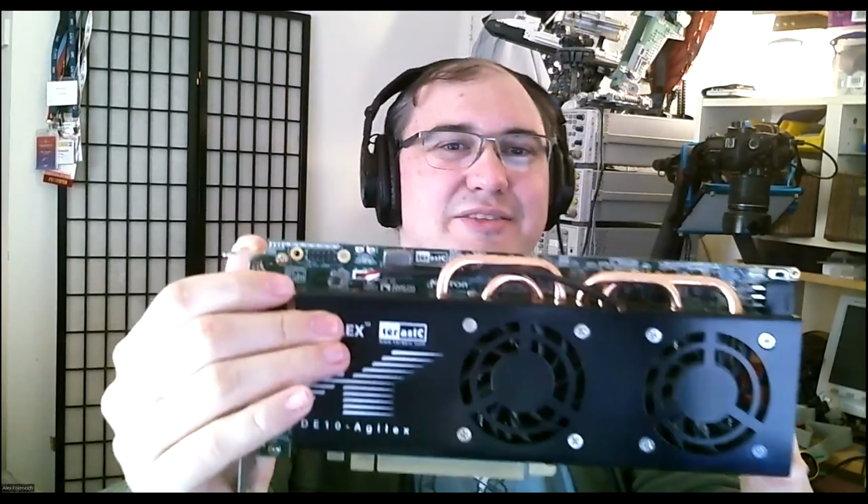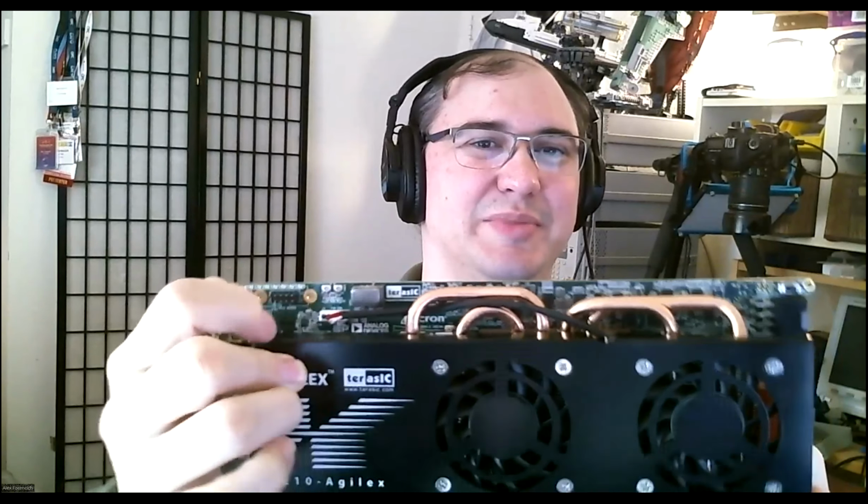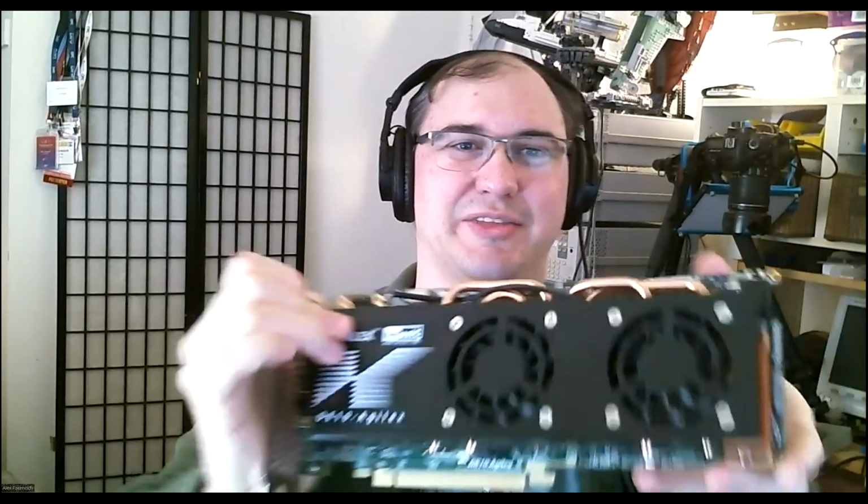One thing I did notice: on your point, you want to use the highest stability oscillator you can get away with. They have some super high stability oscillator on the DE10 Agilex. I need to look at the exact specs, but it's a pretty beefy oscillator at some oddball frequency, like 30-some megahertz. It's supposed to be super high stability. I think it's actually an oven-compensated oscillator. I don't know how much power it consumes, but it's not a TCXO, it's an OCXO. We don't have that. Rubidium is the next step up, right? We don't have that either.